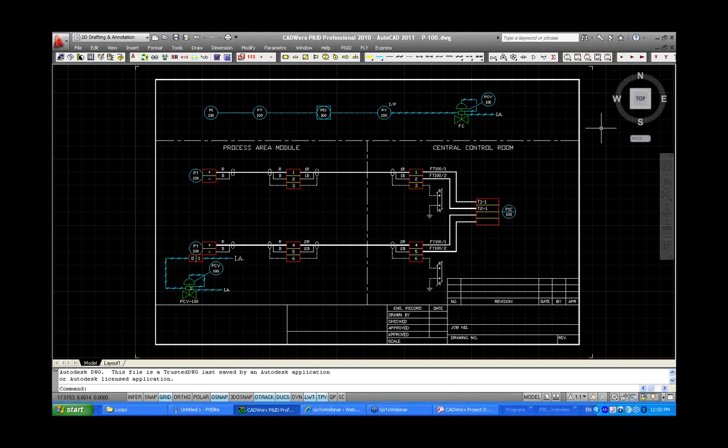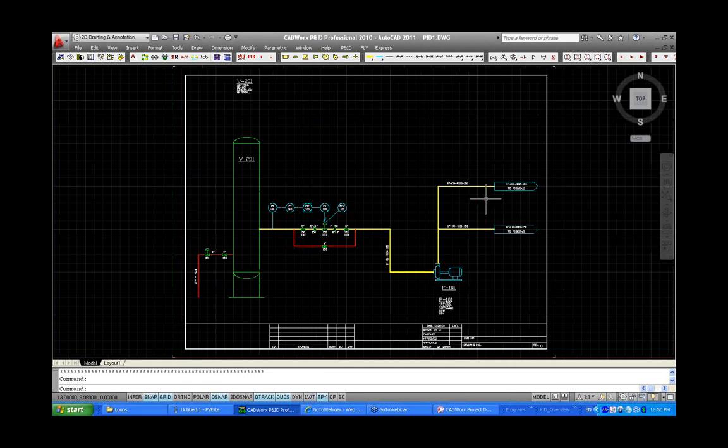Just keep in mind you need a template. You can update the actual table through the editor, and then it's very easy to go in there and simply generate those. Now the next thing is IP. Once we have a project that's completed inside CADWorx P&ID, we have the option of publishing it out to an HTML page, and this project can be uploaded to an internal website, to an external website on the intranet or internet, so certain people can review the information on a specific project.